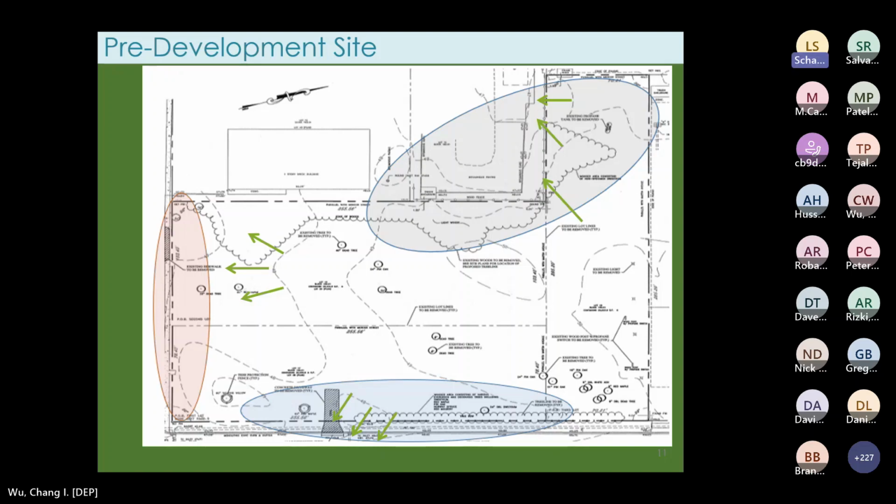And for this project, the design engineer evaluated 3 points of analysis from 3 drainage areas, and those are to the south and east, towards the streets for collection in the MS4, and to neighboring properties to the west. The web soil survey indicated that this entire site consisted of hydrologic soil group D, so not much infiltration was occurring on site. Next slide, please.